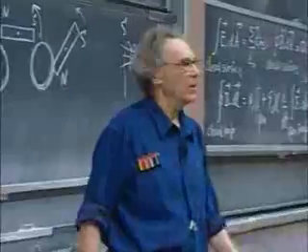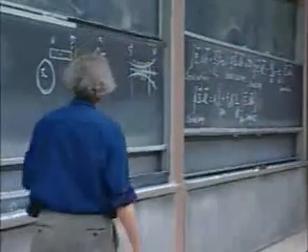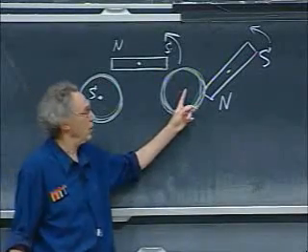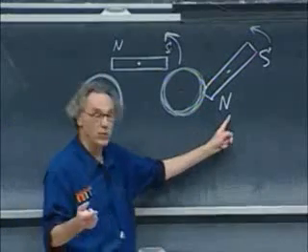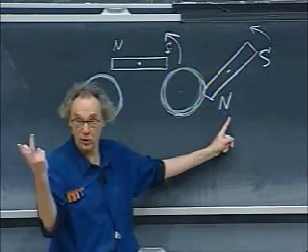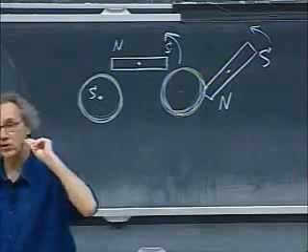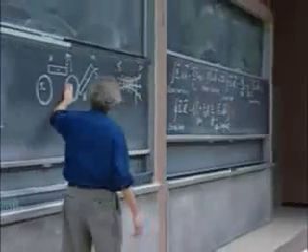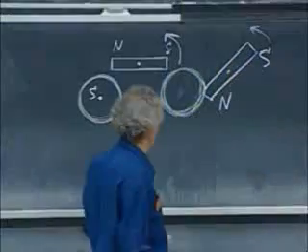Well, the transistor senses that the EMF in the coil reverses direction. It has to reverse direction because if the north pole comes in, the EMF is in one direction, but when the north pole leaves, the EMF, of course, goes in the other direction. You get a reversal. And so what the transistor does, it opens the switch. And so there is no north pole here, and there is no south pole here. And so this thing starts to go around further.